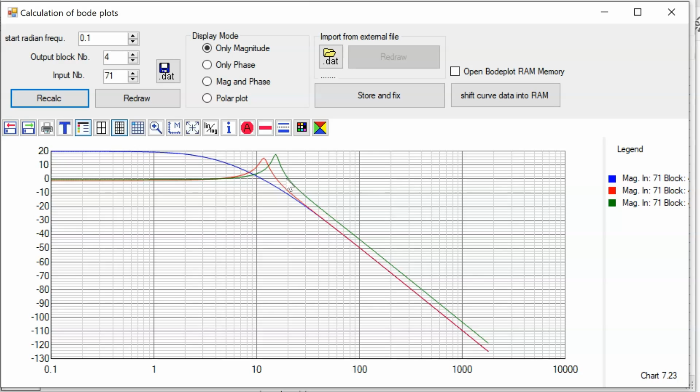This cannot be seen in the Bode plot. The Bode plot can only calculate amplitude ratios of sinusoidal signals. In a Bode plot, the information that now my loop is unstable cannot be detected. So Bode plot information is often very good, but a Bode plot does not contain some information.